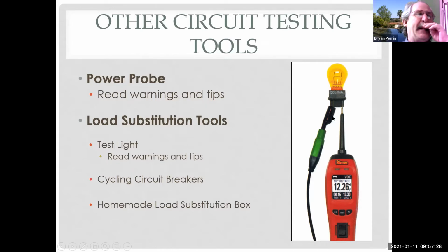Or I can take the component off the car or disconnect the component and apply ground using this lead, touch the other end with this lead, use the rocker switch here to give it power, and see if the motor or light bulb or solenoid or whatever works. Isn't that more efficient than measuring it with resistance on a solenoid? Because what I really want to know is, does the solenoid click? Does it work? So I could unplug it, connect power and ground. Does it click? If it does, it obviously works. That's better than an ohms test and quicker.